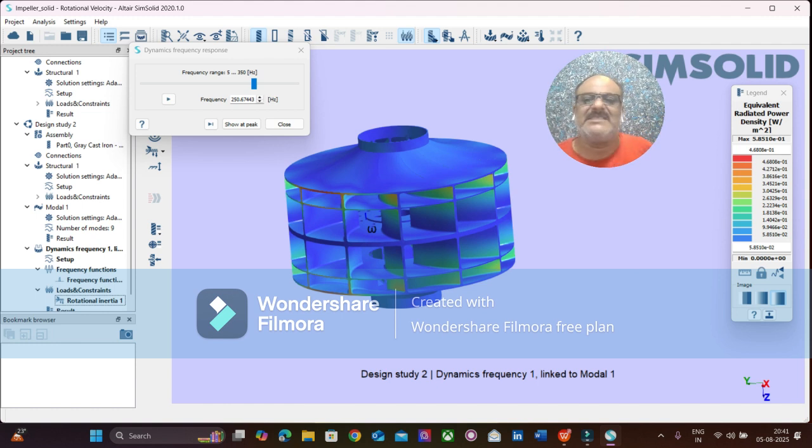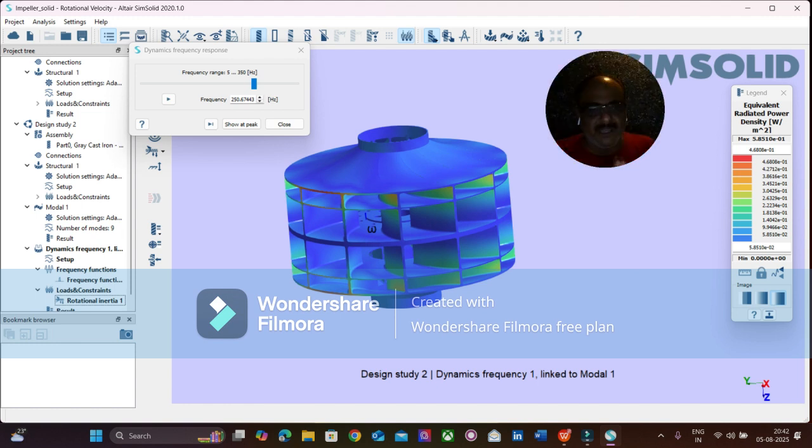This is called the power spectral density, and now we create a pulse out of this. So this particular result that we see here is in terms of a pulse excitation, a super excitation, and these excitations are going to be the input data for the random vibrations. This random vibration is what is going to decide whether the entire system is going to be stable, or whether it is going to have a higher fatigue life, and what kind of durability it has. So performing all kinds of fatigue durability simulation, we do it from this.